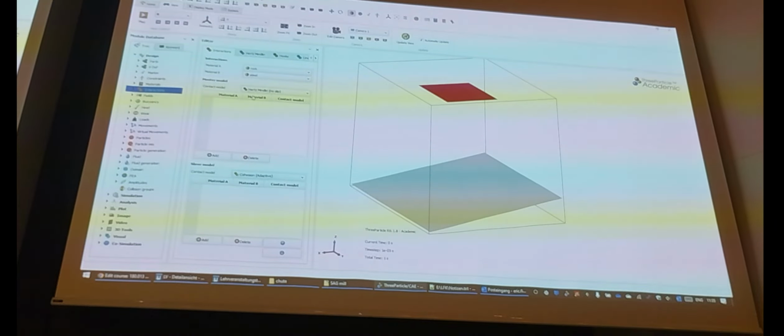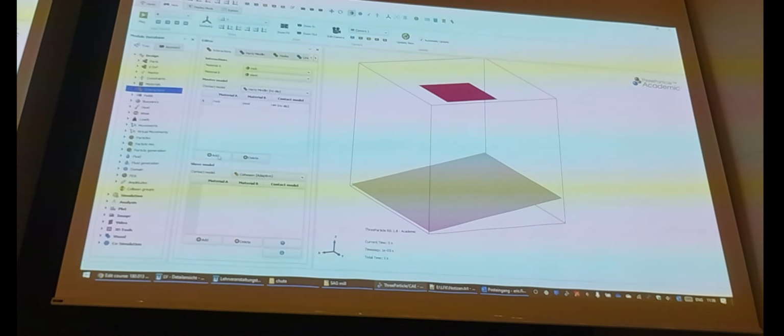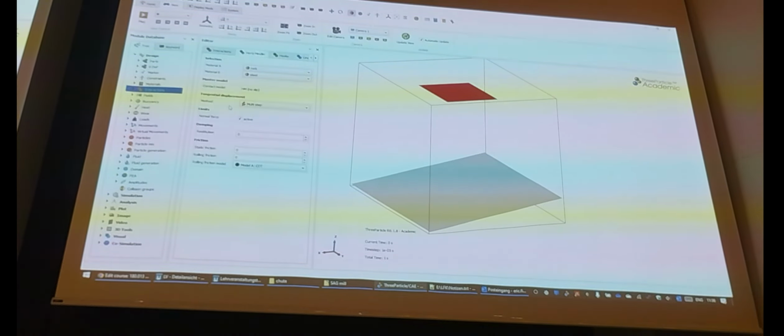And I said, which contact model, please don't look into that, just select the default one. There are lots of them, as you can see, predefined, and you can change any of them in detail, but let's just add the default contact model, dry Hertz-Mindlin no-slip contact. So we say, contact between rock and steel, defined. No slip model, no stickiness, no cohesive behavior, just dry material rock to steel. We double click it, and we have some details to fill in.